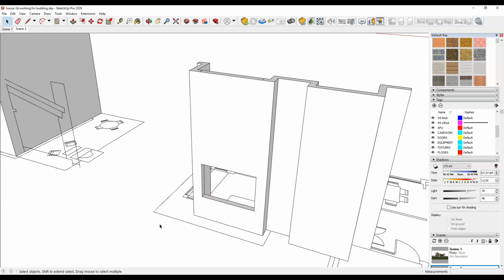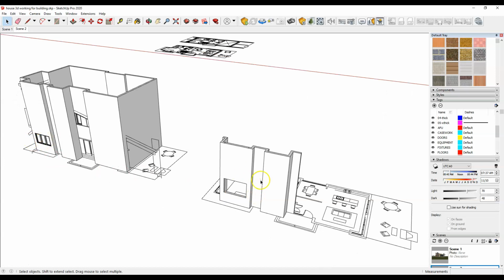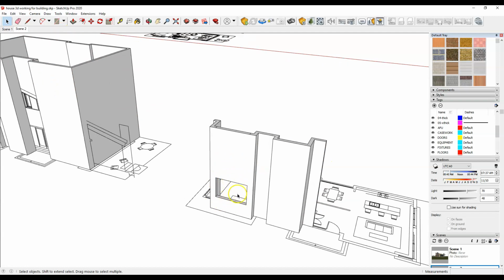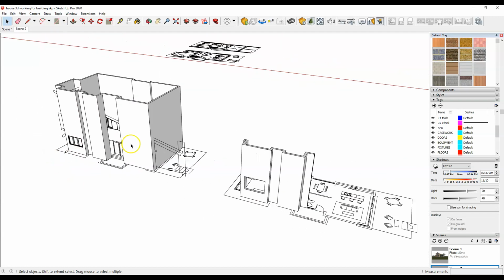Obviously, I'm being a bit sarcastic, but you can see how long it took me to make that hole versus the one that took me to make this. It took me longer to make these pieces of walls than it took me to make probably this whole wall, and it took me much longer to make this one window cut out than it did over here. So could you do it that way? Yes, but the reason why I had you do it this way is because it's just much quicker, much less work, right? So you draw all the walls, then you punch the holes, then you draw the windows. That's sort of a pro tip.